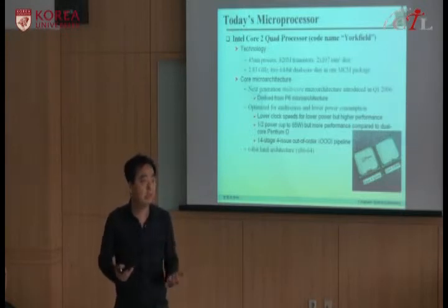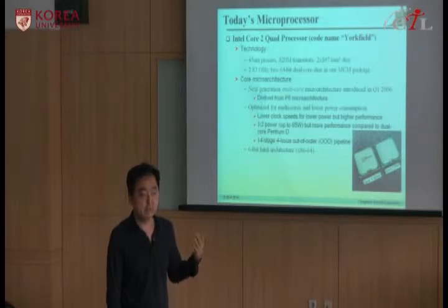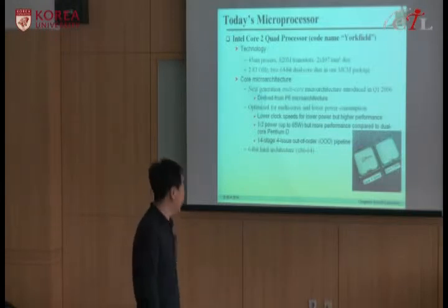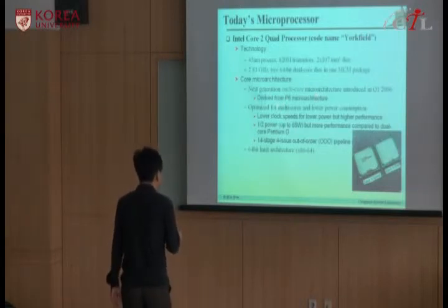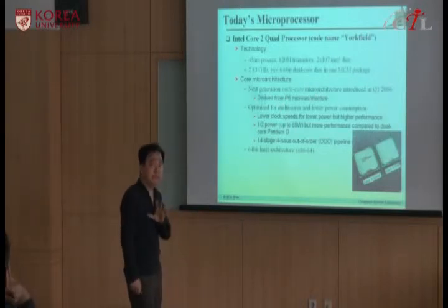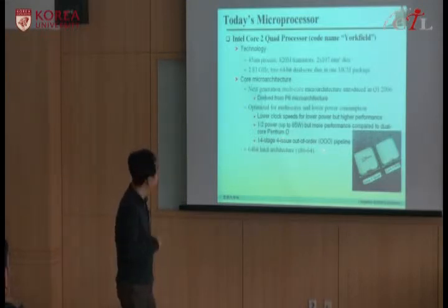It can increase the clock speed, but we don't need that much clock speed, right? Higher clock speed means high power consumption. So instead, the actual pipeline was derived from Pentium 4, which was a 10-stage out-of-order pipeline. They improved from 10 stages to 14 stages, and from 3-issue to 4-issue out-of-order pipeline.